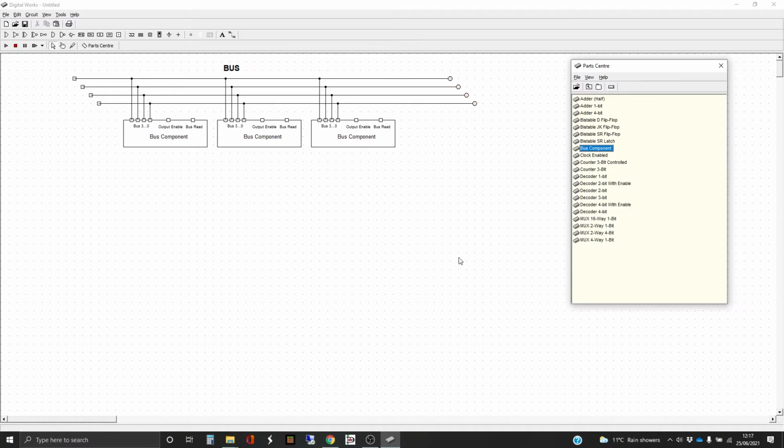So where we're up to is that we've been talking about registers, we've been talking about the bus, which is the way that they communicate with each other, and talking about a specific problem that we have with the hardware, which is that we can only have one component which sees the bus as its output at once, because of a limitation in digital electronics, which is that you can't connect the output of one gate to the output of another and have it work reliably, because they're both of them trying to force their idea of what that data should be.